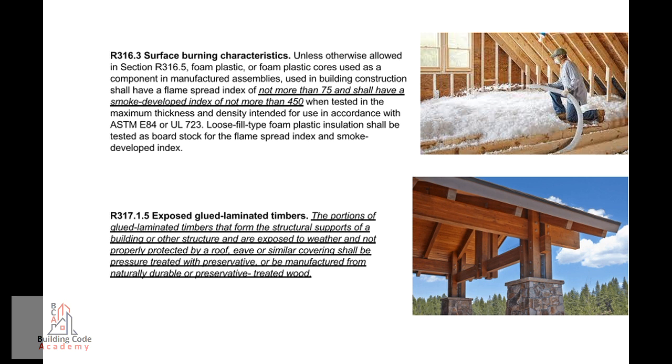R316.3 Surface burning characteristics. Unless otherwise allowed in Section R316.5, foam plastic or foam plastic cores used as a component in manufactured assemblies used in building construction shall have a flame spread index of not more than 75 and shall have a smoke developed index of not more than 450 when tested in the maximum thickness and density intended for use in accordance with ASTM E84 or UL 723.